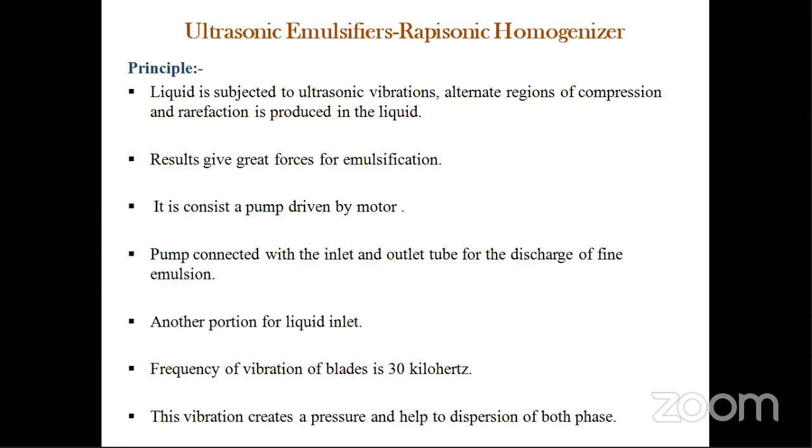When the sonication happens rapidly, what happens? Your mixing process is done uniformly. In this principle, alternate vibrations happen, and two types of phenomena occur in these alternate regions. One is called compression, and the other is rarefaction. Compression creates pressure in the fluid by the ultrasonic energy, and side by side, rarefaction fractures the liquids, breaking the particles into small fragments.